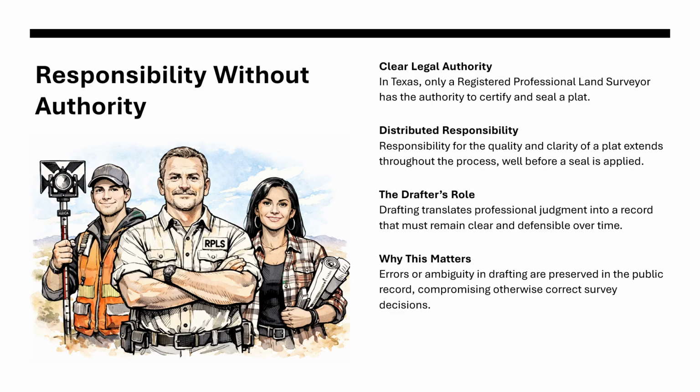The drafter does not decide where the boundary belongs, but the drafter decides whether that decision is communicated clearly or buried in confusion. And this distinction is central to professional practice. A surveyor may resolve a boundary correctly, but if the plat mislabels a bearing, obscures a monument, or creates visual ambiguity, the record is compromised. The error is no longer theoretical, it's a preserved record. And that is why plat drafting carries more responsibility than almost any other drafting you will produce.